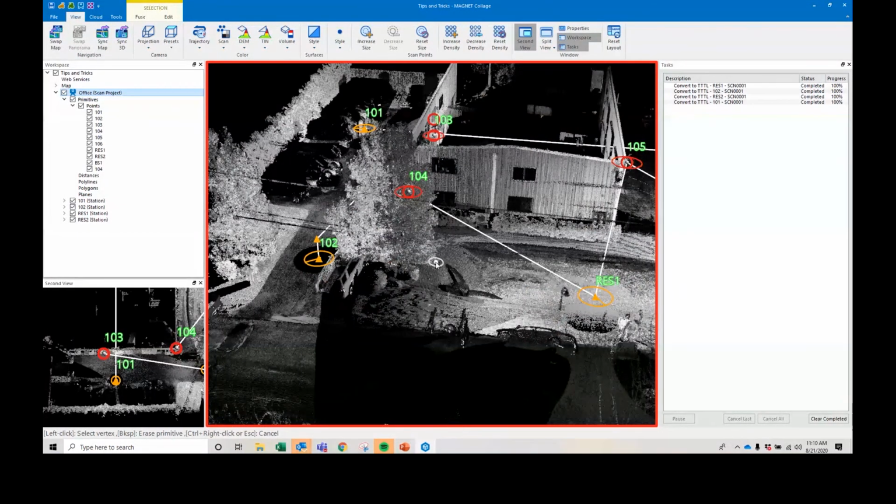The beautiful thing with our Topcon systems, our scanners, is if we set up over known points or we resection, we don't have to do a registration. It's doing what a lot of people call a live registration.